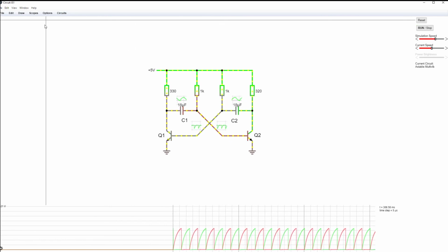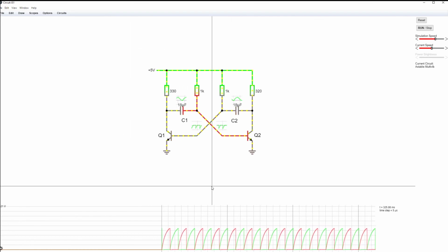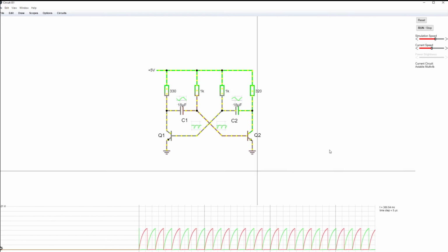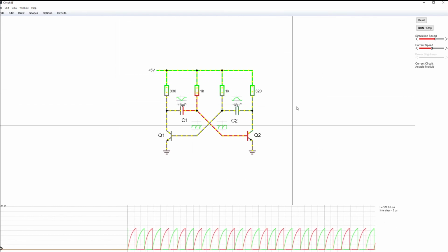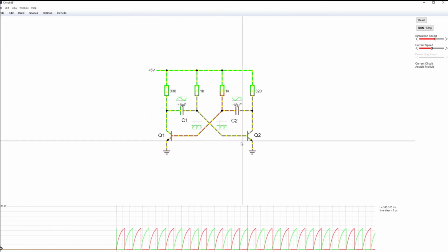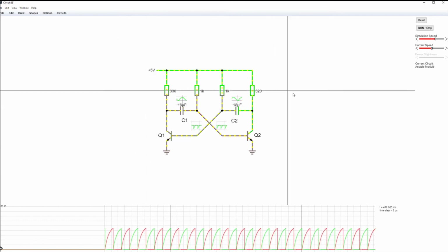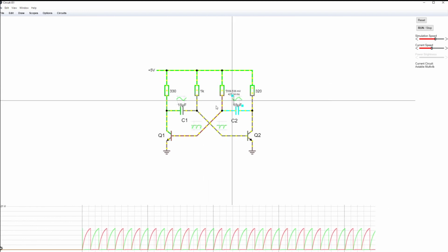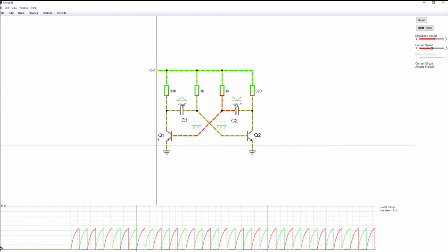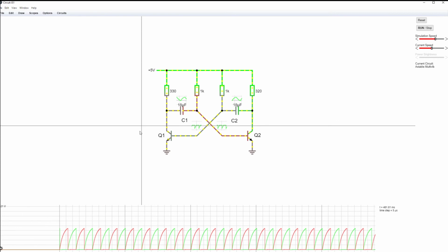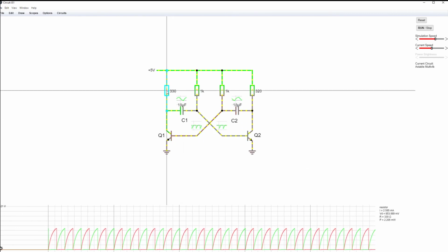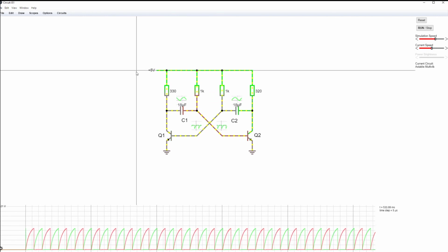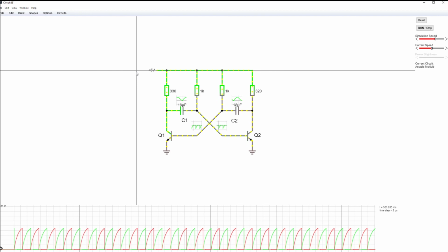So that's with relation to your circuit, and I would like you to go into your circuit simulation software and see if you can obviously build our major circuit, but build a version of an Astable vibrator, and I want you to see what happens when you start playing around with the different capacitance values and different resistor values, because they're going to change the way the circuit reacts. I want you to determine for yourself what they actually change.